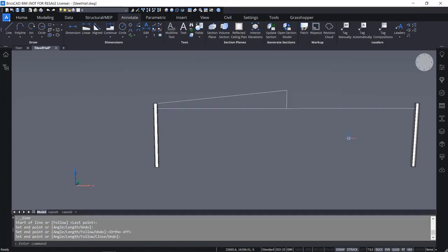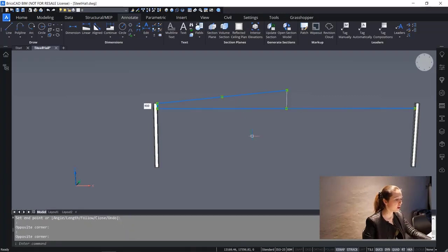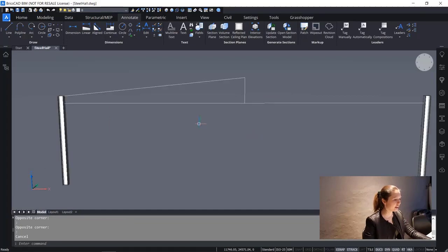So now you have the big beams of your structure, but not the little members that make up the truss diagonals. So what I will do now is divide the upper and the lower line into points that denote a specific division of this line.